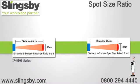Infrared thermometers measure temperature of a flat surface area. The spot size is the ratio based on the distance from the thermometer to the object being measured. The nearer to the object, the smaller the area of measurement. When an infrared thermometer is equipped with a laser, the laser dot indicates the centre point of the area being measured and not the focal point of measurement.